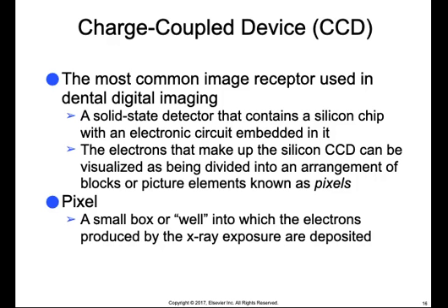The X-ray photons that come into contact with the CCD cause electrons to be released from the silicon and produce a corresponding electronic charge. Consequently, each pixel arrangement or electron potential well contains an electronic charge proportional to the number of electrons that reacted within the well. Furthermore, each electronic well corresponds to a specific area on the linked computer screen.